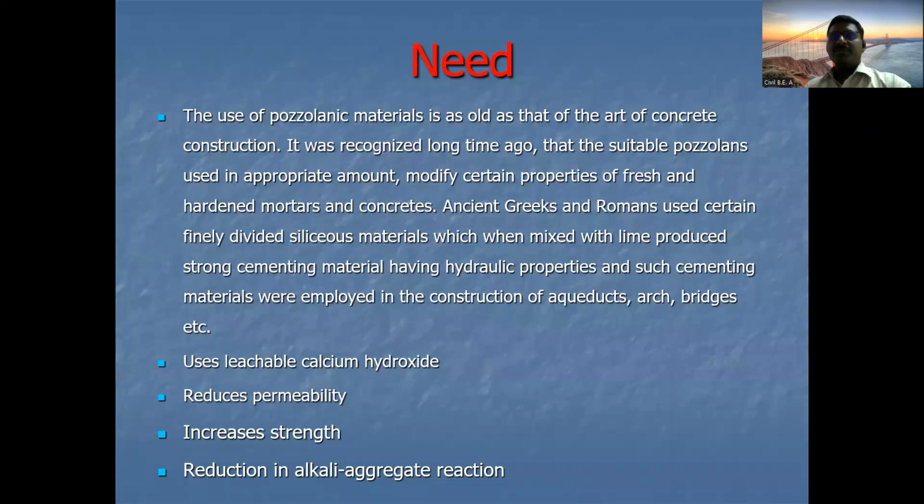From various years we have been using this pozzolanic material in concrete as an admixture. It was recognized a long time ago that suitable pozzolans used in an appropriate amount modify certain properties of fresh and hardened concrete, or hardened mortars and concretes, which are improved or modified if we use pozzolanic materials.